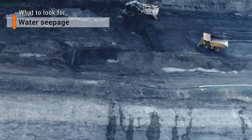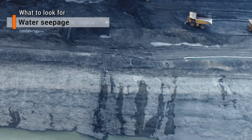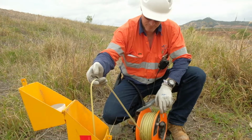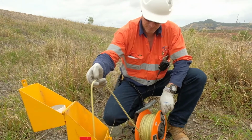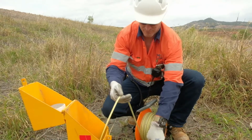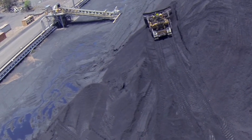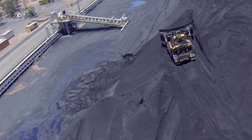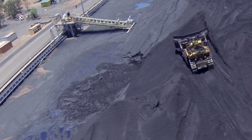A sudden increase or decrease in water seepage from a dumped or excavated slope face observed either visually or measured by instrumentation such as piezometers or standpipes. Water seepage from coal stockpiles is particularly critical for identifying the potential of failure in this type of dumped slope.